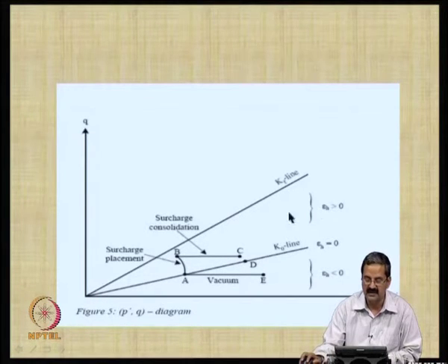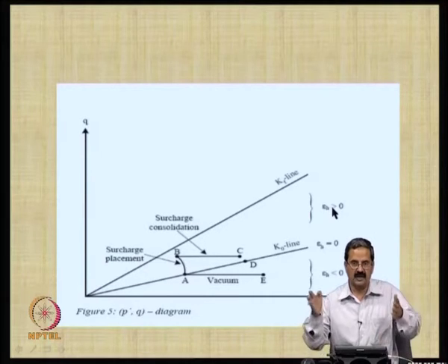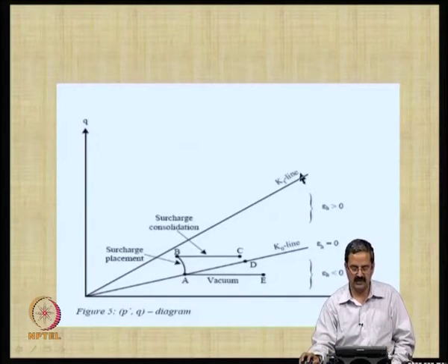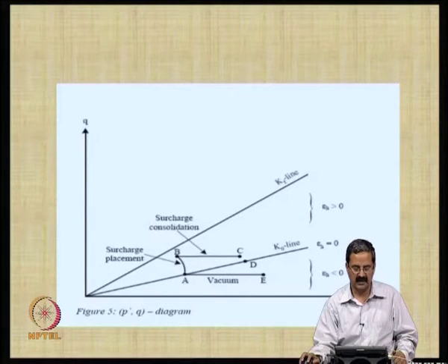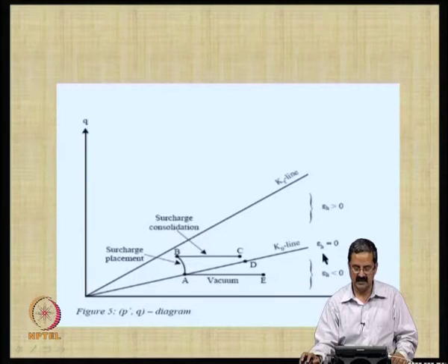You can see that there are always some horizontal strains there, because the moment the soil state, we call it, is in this range, there are always some horizontal deformations that exist. But if the horizontal deformation is too much, then total collapse takes place, right. The horizontal deformation should not be too high, because it is a combination of shear and volumetric strains, and it should not lead to failure. So, you can see that this is a region at which horizontal strains are higher, and this is a region along which horizontal strains are 0.